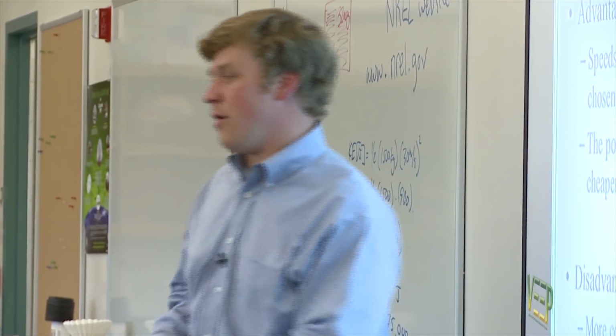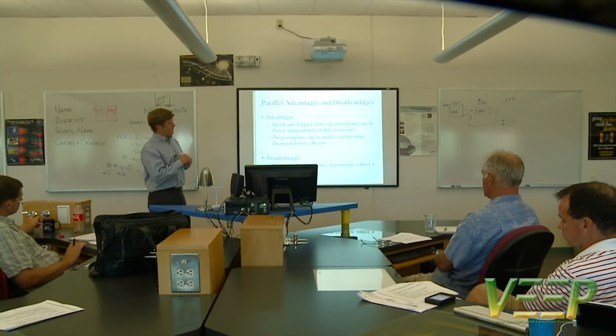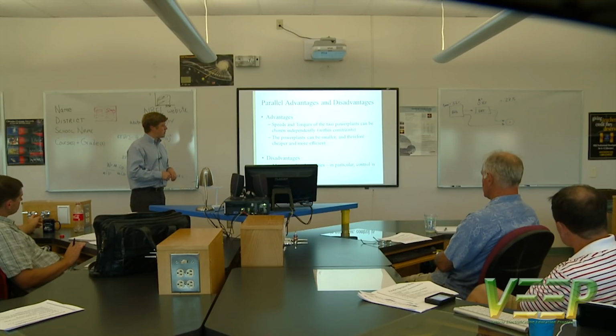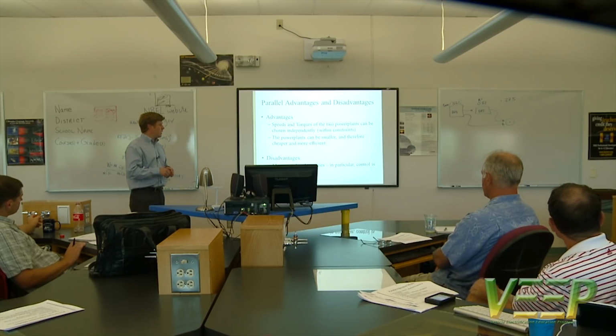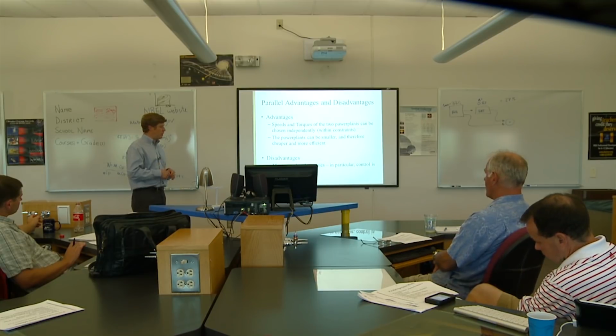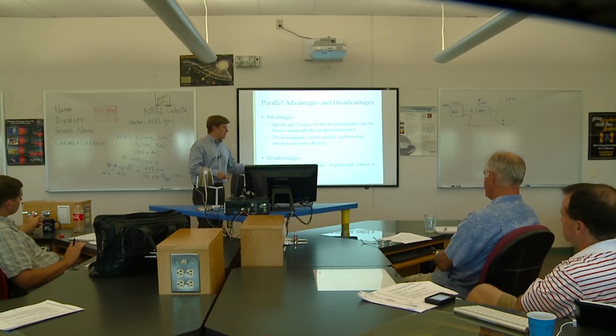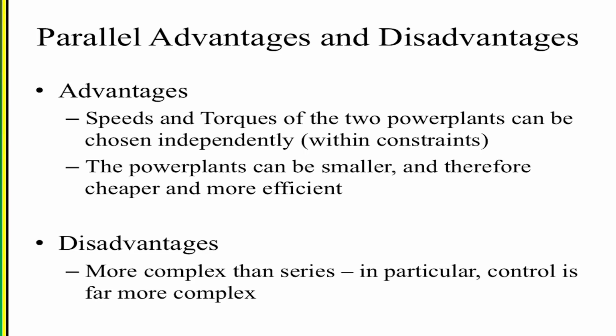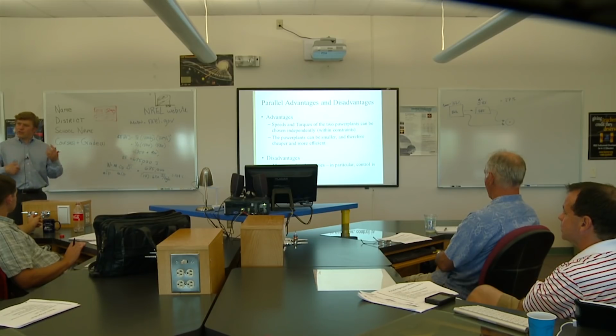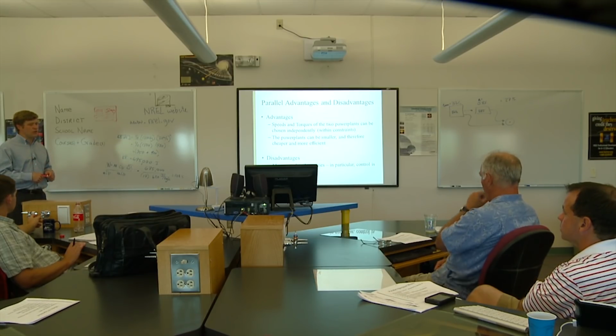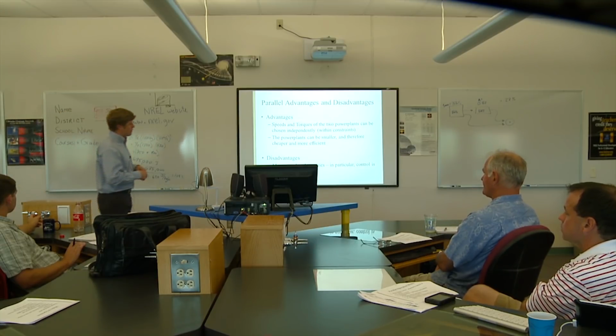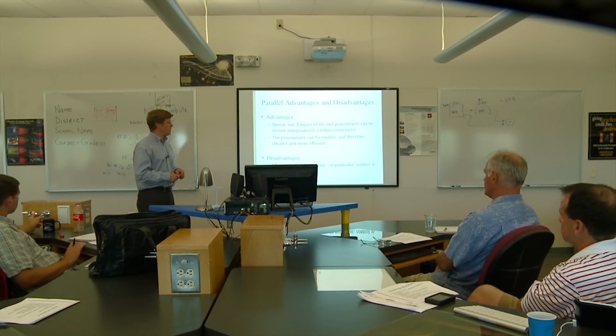They're more efficient, again, because we still have that direct fuel to wheel sort of connection that can be a mechanical connection and can be very efficient. The disadvantage is that they're complex to control in general. So for instance, if you've ever driven any of the Honda cars or whatever, you can feel the engine turning on and turning off. You can, because there's basically a very direct mechanical connection between the engine and the wheels that wouldn't be there in a series.